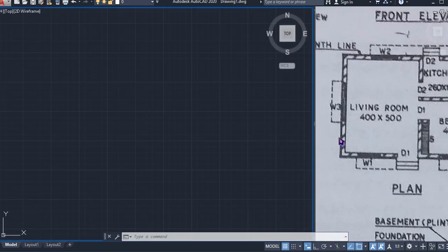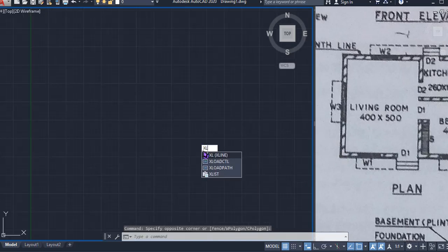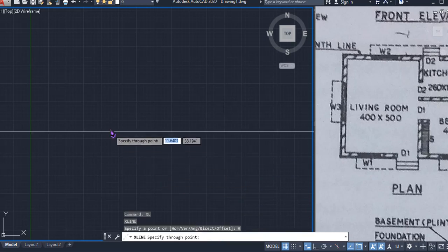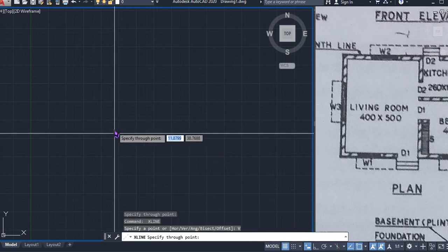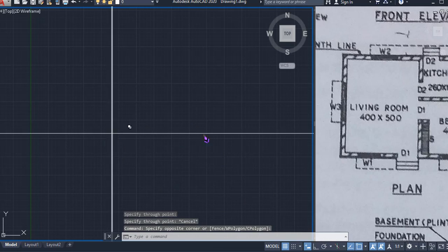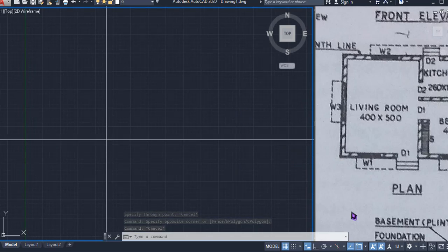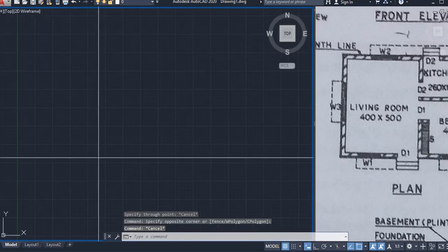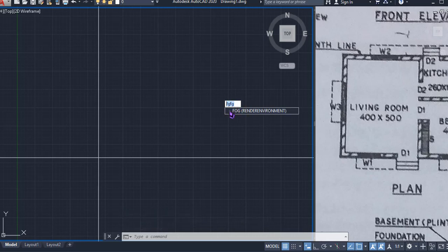The first thing, we'd like to pick up the bottom left corner of the building simply by using construction lines. I'll pick a horizontal line and a vertical line, as this particular node indicates the bottom left corner. Next, I'd like to turn on dynamic input simply by pressing F12. If I hit F12, it will be turned on. You can test it by typing here. Everything, if the dynamic input is on, will appear right near your mouse tooltip.